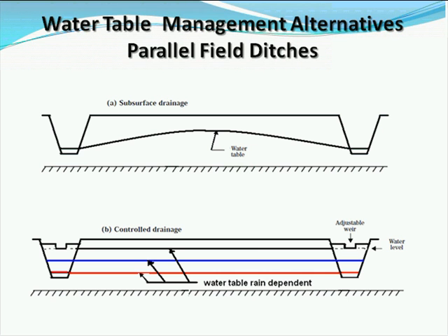And then through the course of the season, the crop begins to get higher, but you go into a drought situation. Well, then your water level continues to drop, and without any replenishment, by the end of the season, you may have the control structure in place with the capability of controlling drainage, which would actually be controlling the discharge.